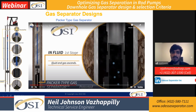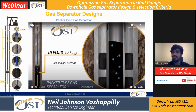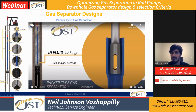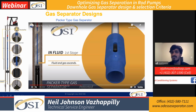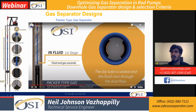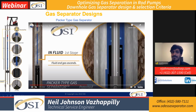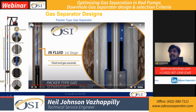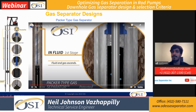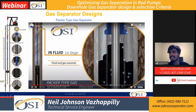So the fluid flow coming from the formation is directed inside of the separator. Now the way it goes around the dip tube is with our patented intake collar section right here, where we are not going straight up inside of the dip tube and going to the pump. So we have it redirected around the dip tube, and it goes to the inlet section.